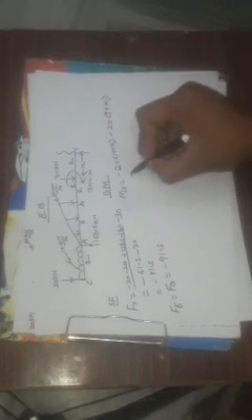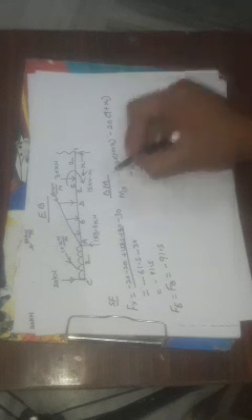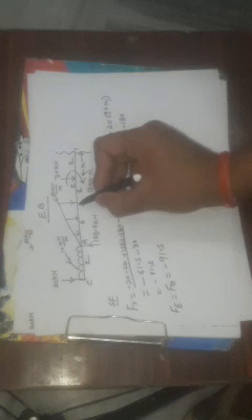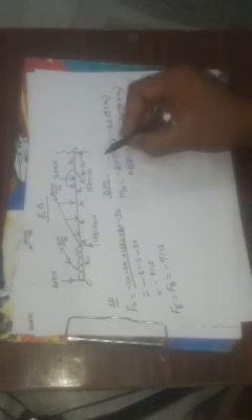Then it will be minus 20 into 9 plus x. It will be plus because it's an upward force, and for bending moment an upward force is positive. Then 158.5 into 6 plus 2, 8 plus x. The total weight of the UDL is 180, into this distance 2 plus 2, 4 plus x. And then there is a moment of 15 kilonewton meter. It is in the clockwise direction.